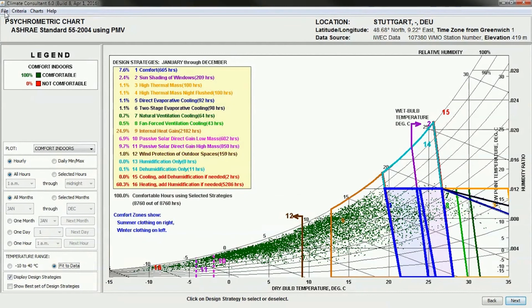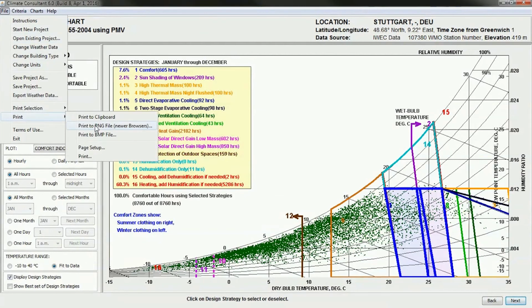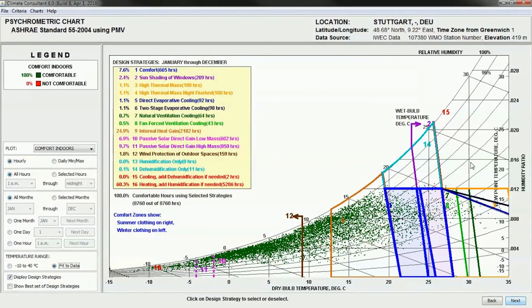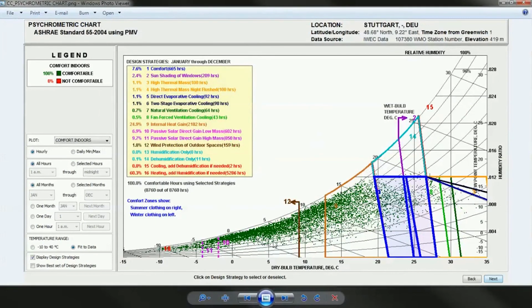In order to output this, go to File, Print, and then you can print to PNG. And this will create a PNG file quite quickly, actually. I'm going to drag this over, and you'll see that this is now a static image that you can import into InDesign, create a new layer, and annotate over the top what's important about this and what we should pay attention to. If you want to be really fancy, importing into Photoshop and customizing the colors would be a really nice step.